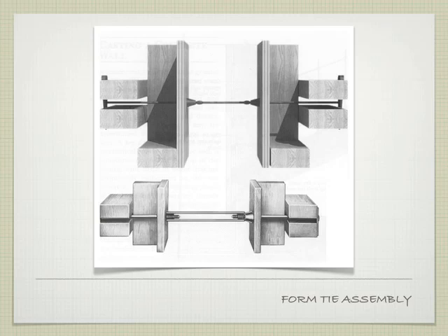So if I had this against the wall like this, and I had another piece of plywood on the opposite side, this would maintain an equal distance. If you imagine it on a grid pattern on the sheet of plywood, it would keep the sheets of plywood exactly the same distance apart. The reason that this is so long is that I have my stud running vertically, then my wailer running horizontally, then that little metal clip that will slide in here, and it's on a slight taper so that when I slide this in and pound it into place, it'll hold this nice and tight against the formwork, which then holds the plywood panel in its correct position.